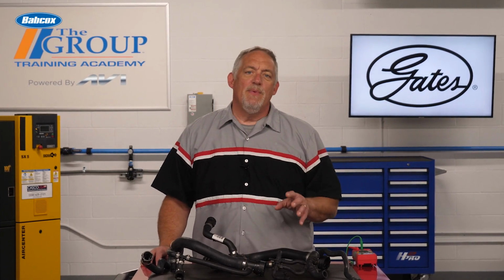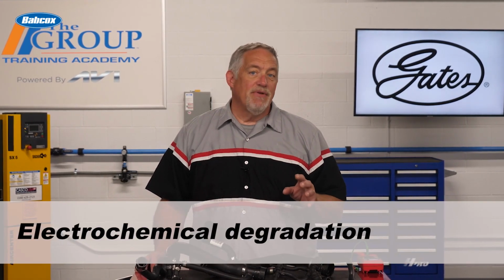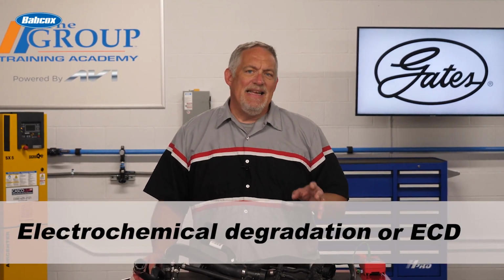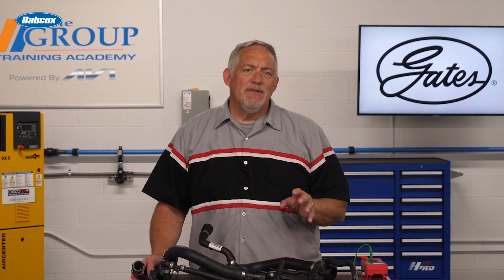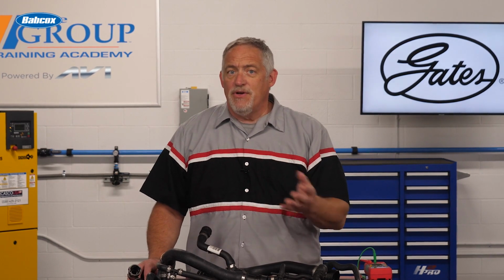The modules in these hoses are essential and include sensors which measure flow rate and temperature, communicating directly with the ECM. The most common failure mode on a standard molded hose is electrochemical degradation, or ECD. ECD is caused by an electrical charge being carried through the coolant from component to component.